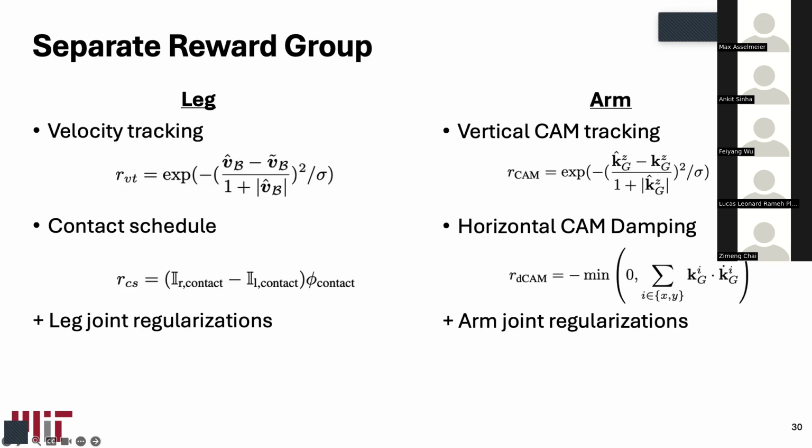Yes, angular part. So the centroidal momentum is actually six dimensions. This is only the sixth part. We don't consider the linear part, only the angular part, omega x, omega y, omega z, and it is the omega z part in the momentum. Yes, yeah, you're taking it.